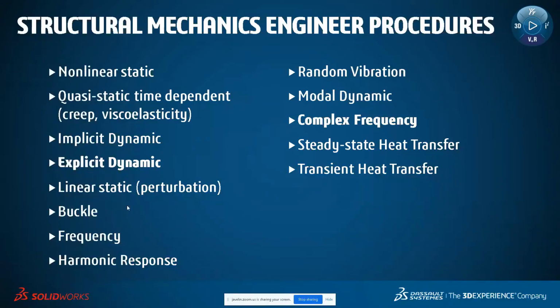You can also do the SPH elements if you're doing fluids, or if you've got something that could potentially explode when it hits something. A lot of times SPH elements are used to mimic a bird strike, like a bird hitting an airplane wing or any aerostructure, and the bird's kind of going to explode. A little bit gross, but a lot of times that's what's used.